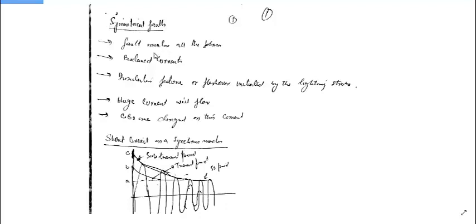You will see that when a three-phase to ground fault occurs, all the phases are close to each other and the currents are balanced. We know that there is no neutral current. So the three-phase fault and the three-phase to ground fault are the same, because in both cases there will be no current through the neutral, and the fault current flowing through the phases will be balanced. They are equal in magnitude and displaced by 120 degrees from each other.